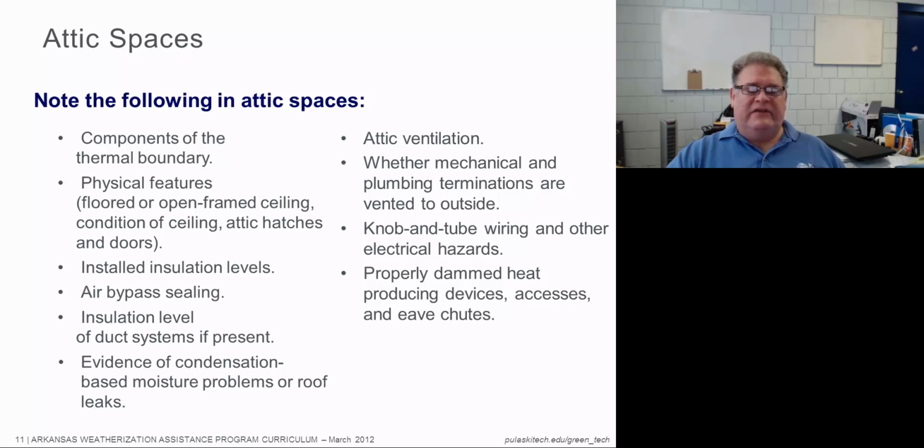So how about evidence of condensation or other moisture problems on the roof or on the sheetrock below? That would indicate that we've got a good, strong bypass that's putting a lot of moist air in, or perhaps an exhaust fan for a bathroom or a kitchen or something like that that's not properly ducted.